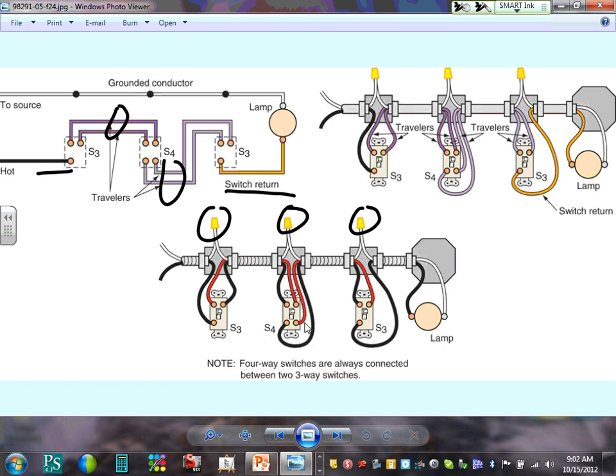When it comes to the takeoff, Adam, and we do three-way switches, you're going to come here and take off this as a three-conductor cable, right? Between the two of them, a three-conductor cable, of course with a ground. Not a two-conductor cable. So that's where wiring becomes a big deal when you do the takeoff. Not like you guys are going to go wire. I hope you can wire.